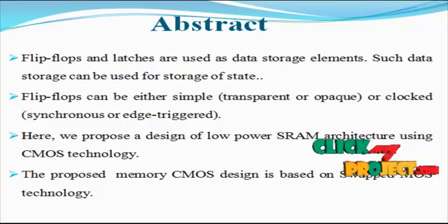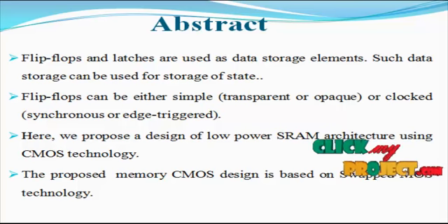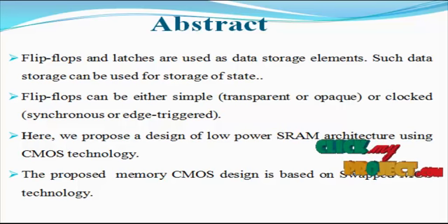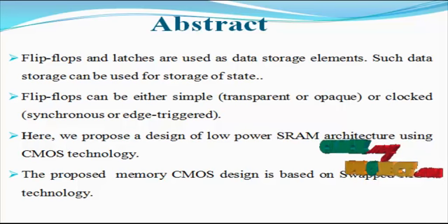In this paper, a new approach towards the design of a memristor based non-volatile static random access memory cell, using a combination of memristor and metal oxide semiconductor devices, is proposed. Memristor and MOSFETs from Taiwan Semiconductor Manufacturing, based on 180 nanometer technology, are used in the form of a single cell.